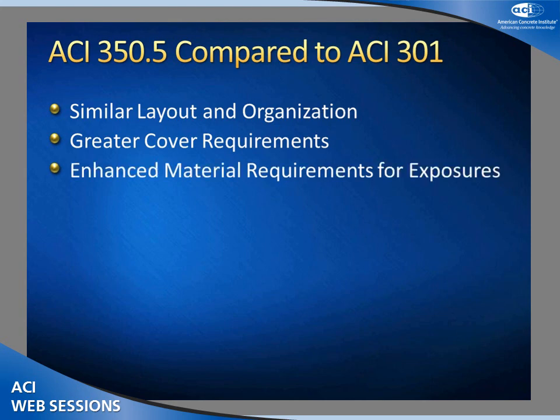We also have enhanced material requirements for the exposures. When you look at supplemental cementitious materials that might be used, levels of cementitious material required for various exposure conditions, we're very specific. Probably you'll find we're a little bit more conservative than what you'll get in ACI 301. And we cover shotcrete.